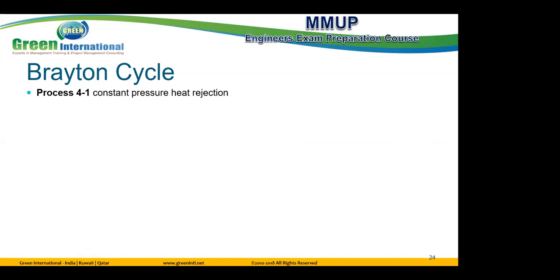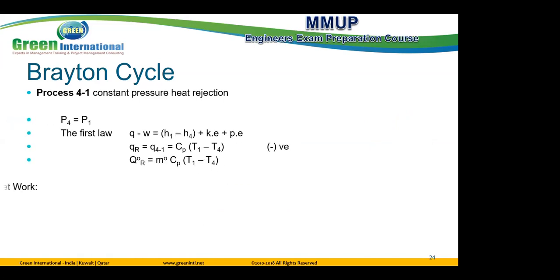Finally, the heat rejection, but it is not used a lot. Finally, how to calculate efficiency. This is an important part. Net work is equal to net Q. Net work is turbine work minus compressor work. Net Q is equal to Q added minus Q rejected.